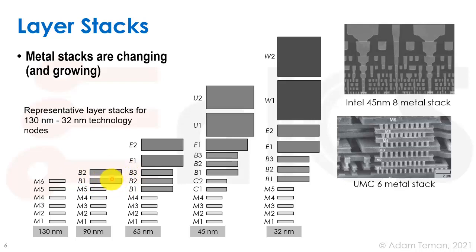We have much larger minimum widths and minimum spacing, but these are not used for fine signal routing, just for top layers. In this case, we have 2 types of layers: the lower layers, which have the highest lithography with minimum width and minimum spacing that we could get into our design rules, and at the higher layers we have something much bigger. The vias are much bigger, etc., so we can deliver more current and have less resistance.